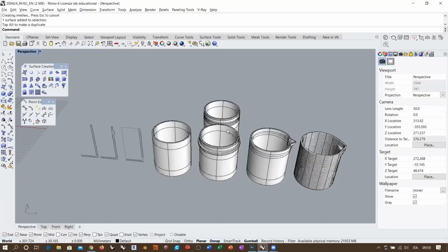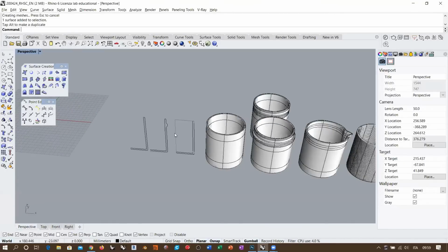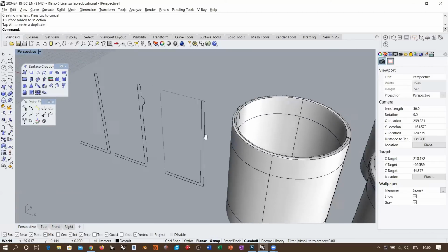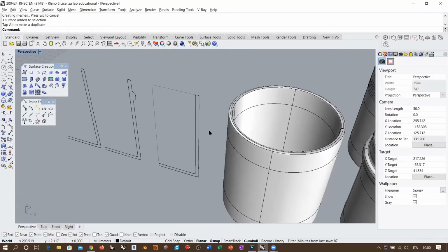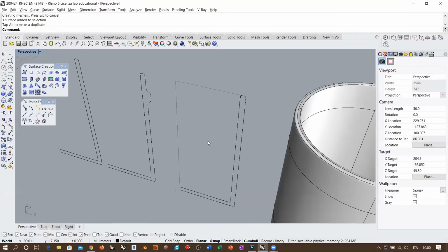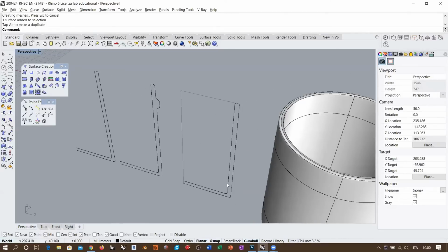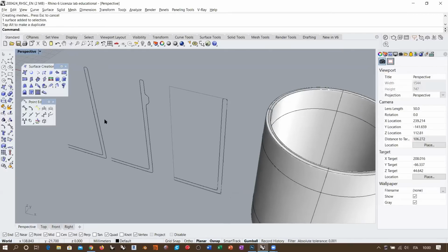Then there are other types. Well, there is another type of Revolve surface, which is actually somehow problematic, but it can be useful to create some nice, let's say, complex Revolve surface also from the rotational point of view. So you might know, for example, that there is a right-click command which is rail revolve, where you are allowed to select not necessarily a circular revolve, but a revolve which is determined by a rail curve. So you will have profile curve, axis curve, and rail curve.